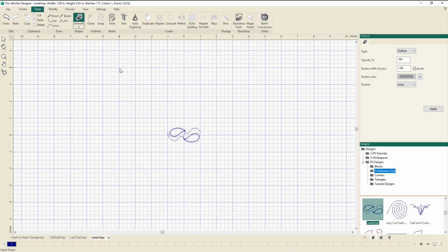Left mouse click and hold. And I'm going to drag my hexagon across to the +4 grid line and the -4 at the bottom. And then once I've got that, I'll release the mouse key, and then I'm going to just go to Q to select the object so it finishes the function.